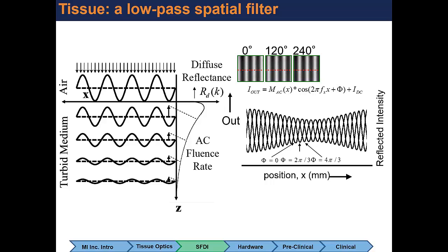The reason why it looks so easy here is because you've kept your DC constant across the whole field. In reality, your DC can be changing at the same time, and then extracting the AC from the DC may not be so straightforward just by taking one measurement. In fact, to do it mathematically rigorously, you need at least three measurements.